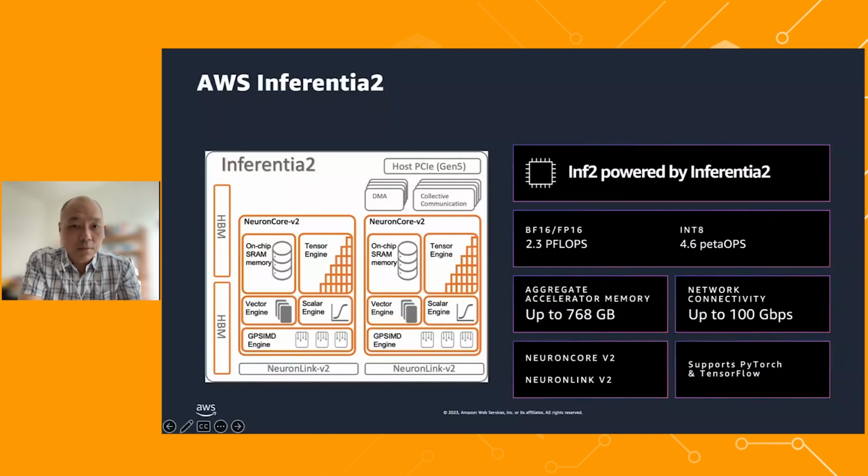The result is that fused ops for data movement can be run in parallel at the same time the compute engines are doing their job. The tensor engine is doing the matrix multiplication, and the scalar engine is doing the activation, and so forth. So we parallelize as much as we can from an operation standpoint.